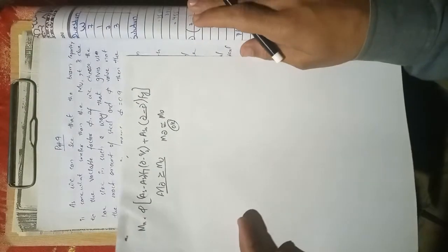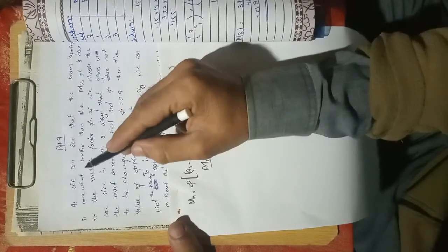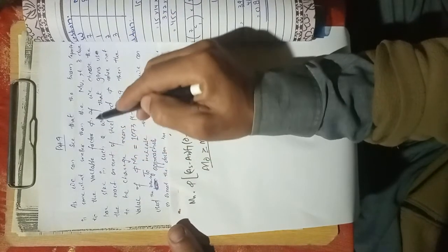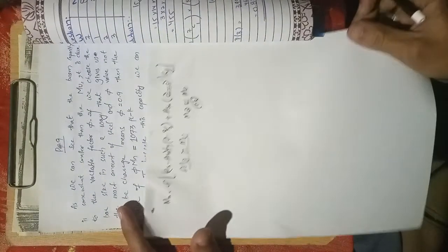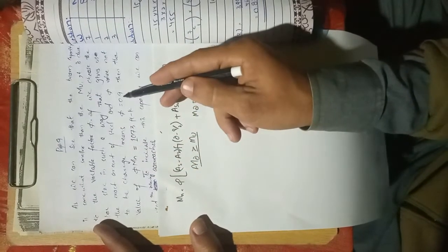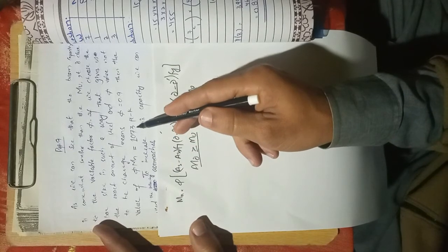We have different options, right? Now what are those options? As we can see, the beam capacity is somewhat smaller than the Mu, and it is due to the variable factor phi. If we choose the bar size in such a way that gives us the exact amount of steel and the phi value is not changed, meaning the phi value is 0.9, then the value of phi Mn is 1073 feet-kip.